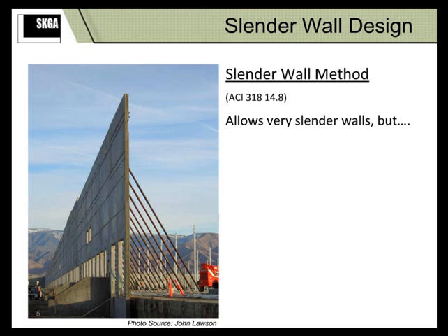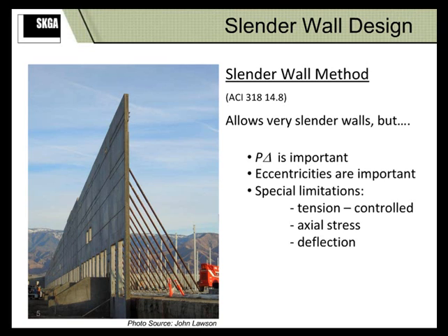There's two other methods for designing walls. One's the empirical design method, and another one's designing it as a compression member, but they don't allow slender walls. The slender wall method allows very slender walls with some important restrictions.